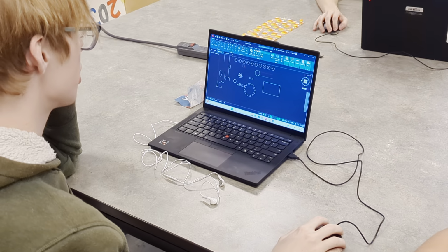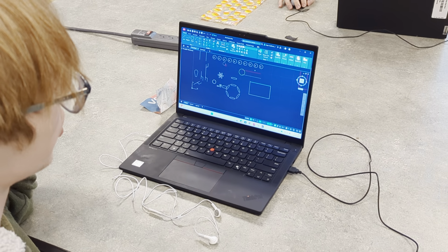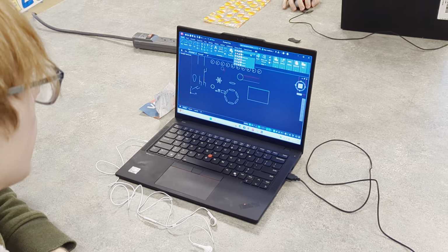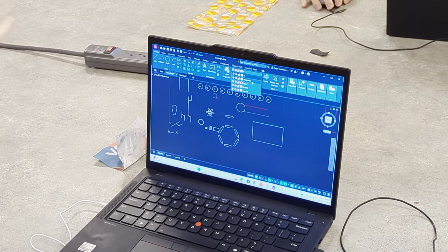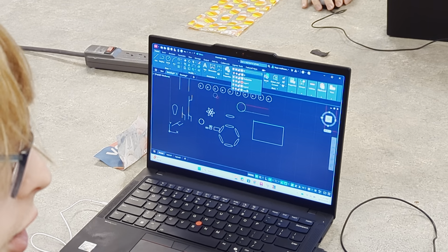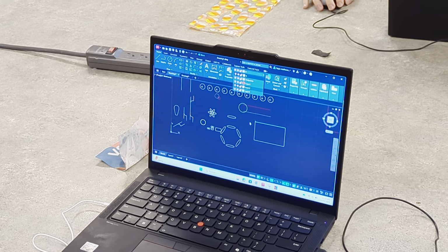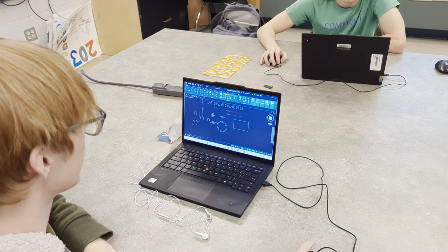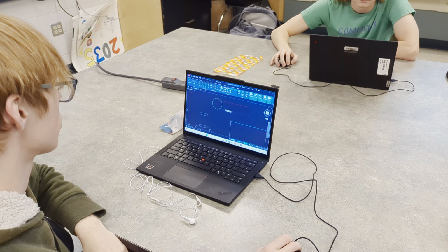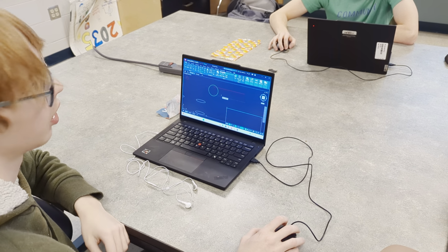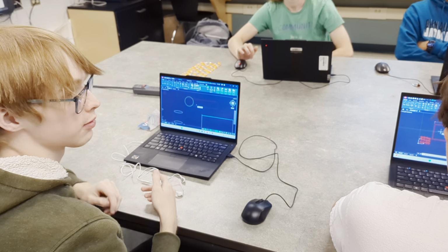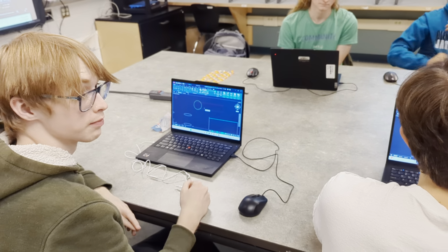And one of the other things you need to make sure to do when you're setting up your drawings is that you have your different layers enabled, so that you have a different layer for, say, your walls and your doorways and your windows and your furniture. So you can have different layers be different things, different line types. So you can have a dotted line, a full line, different colors. Maybe if you want to have a fence somewhere, you can put different lines and different styles of lines for different layers when needed. Excellent.